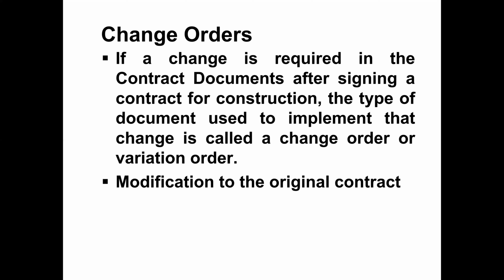But every change will be compared with the original drawing and with the final drawing. And then the impact on the price will be checked. It will be calculated based on whatever rates are there in the contract document. If something is not there, or there is some additional or new material, then the rate will be new. But all three parties have to agree with all these change orders.